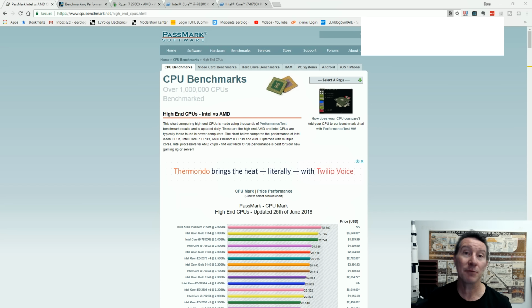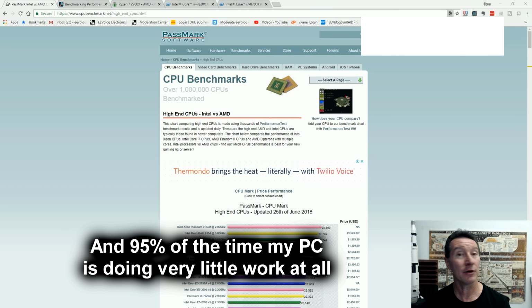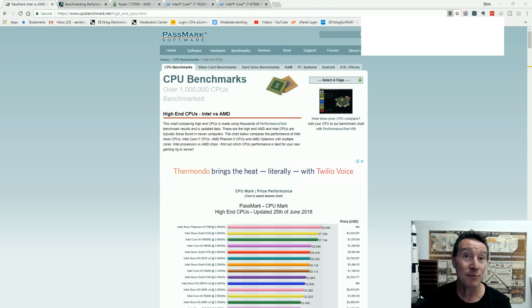As for the other elements in the system, the CPU cooler, a lot of people said, oh, that's a crap cooler, it's not going to do the job. Well, sorry to tell you, it actually does do the job. Further on in this video, I've added some screenshots of CPU temperature tests that I've done, not only when I'm rendering, but also running the processor flat chat. And if memory serves me correctly, during rendering, it's under 60 degrees Celsius CPU temp, and under absolute full load, flogging all the cores at 100%, it's 70 degrees or under. So it does the job quite okay. There's no reason to get anything else. I liked the low noise fan in it. Probably could have got lower noise, but anyway, it's a reasonable cooler, and it does the job. For those who are saying it doesn't, sorry, data shows it does just fine.